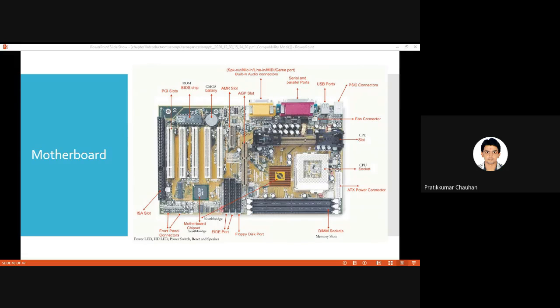Okay. So 2.5. If the slot has the number 2.5, it means DDR1 can be installed in that slot. If the slot has the number 1.8, it means DDR2 version of RAM can be installed. If the slot has the number 1.5, then DDR3 can be installed. And as per the current market trend, in the new latest series of laptops and PCs, you will find 1.2, where the DDR4 category of RAM can be installed. Is it clear now?